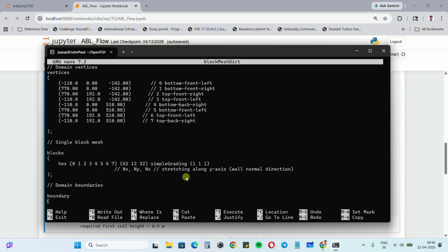And also I am not using gradings. Our heat exchanger is basically floating in the domain. I have found that with grading, when you have floating objects, it struggles to get the snapping proper. I always found that there are some cells which are of high skewness. So I have followed uniform grading, and I will have local refinement or volume refinement to get the first cell